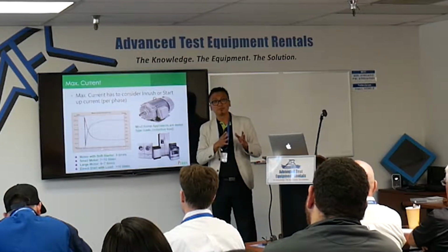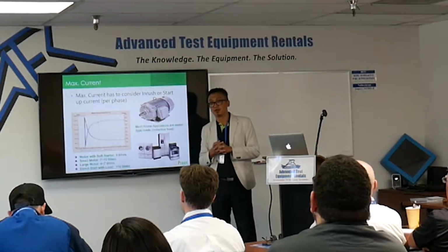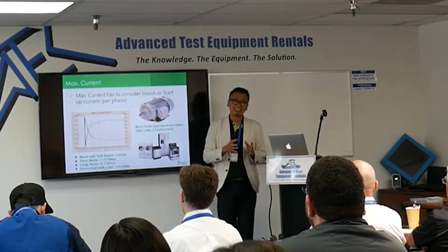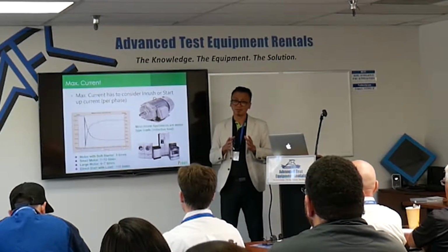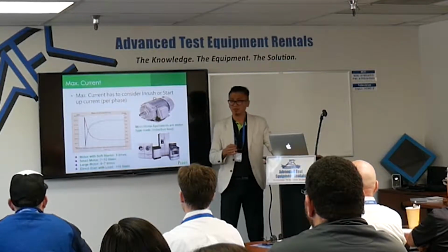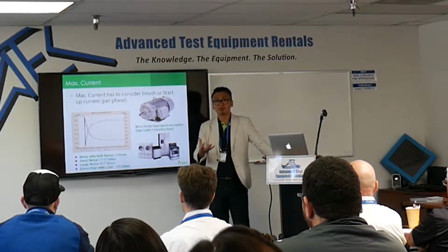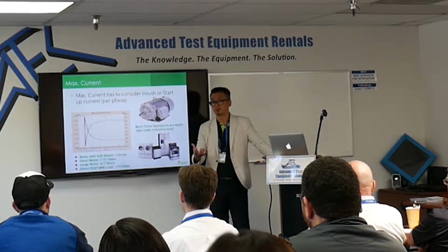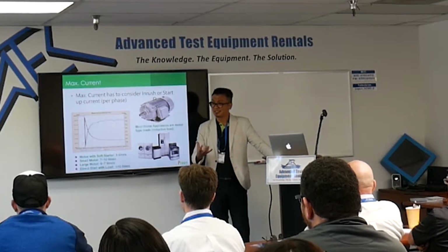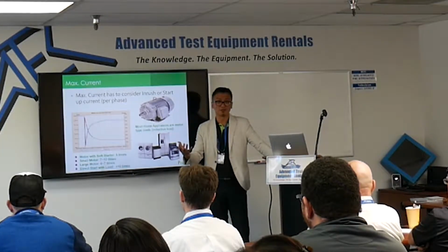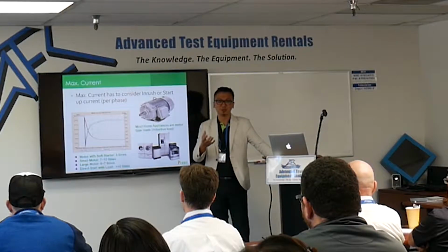No matter whether it's a linear power supply or a switching type of power supply, we will be concerned about the maximum current you need. Most customers will say, okay, I have a motor with 10 horsepower, and they expect they just need maybe 10 kVA of power supply, but it's not really true.